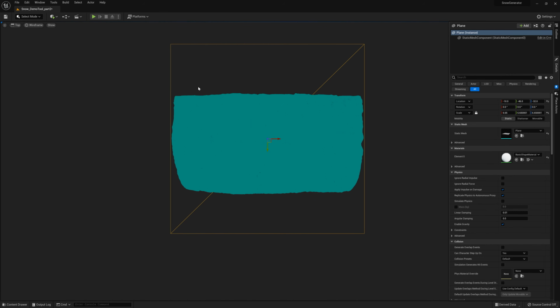So as you can see, basically what is happening is our model is getting mapped to fill the UV space based on its largest axis. So in our case, the largest axis would be its x-axis. So it takes that axis size and then tries to fit this model into the UVs using that axis. The problem with this is, obviously, depending on the size of this model. Say this model is 20 meters across by 10 meters.